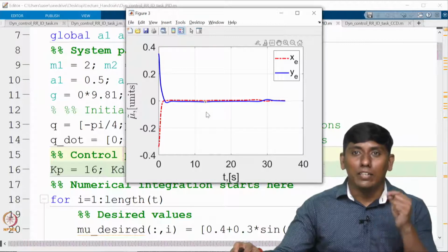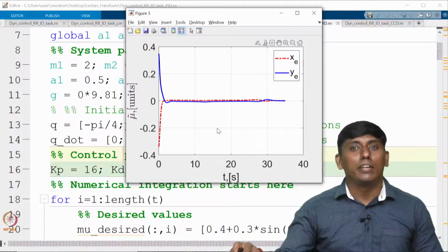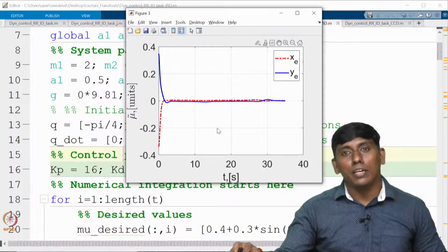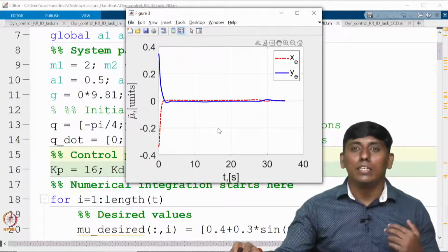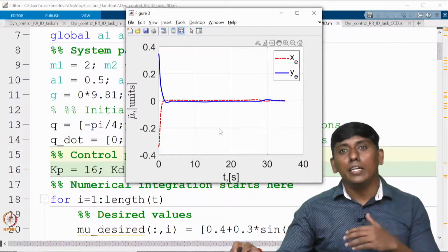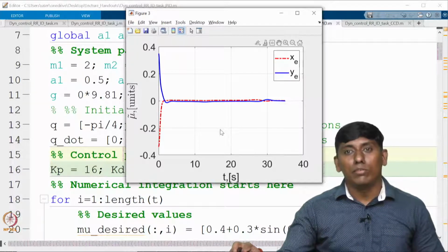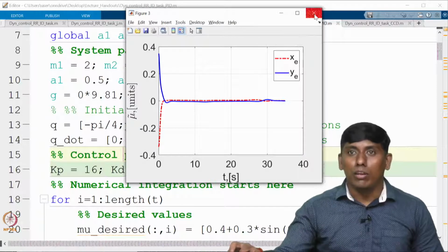Now the integral is actually making, you can say, pushing different regions. This is what I want to emphasize: PID control is not the most commonly preferred in the robotic manipulator community, rather than PD, because the I term can end up with what you call windup. So that's why we can avoid this particular PID control. Now you are clear.